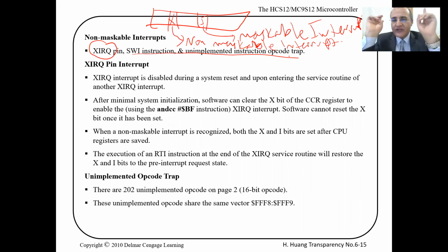So the first thing, it's only one time. When you first start your microcontroller, after the power on reset, you can go do the X bit and make it a 0. Yani, you enabled the non-maskable interrupts for the first time. Then you cannot change its value until you do another reset later on. Yani, for a customer, he cannot do it. Okay, you cannot do it by code.